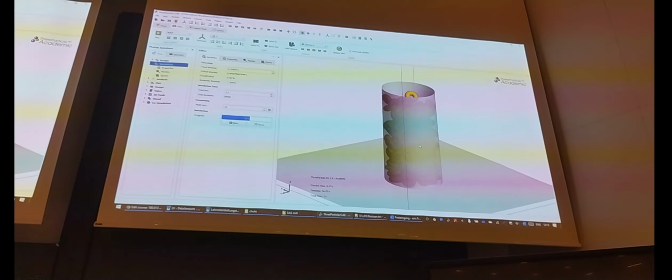If I increase the time step to a certain point, let's see what's happening. I increase it to 0.01 and I start, and the thing suddenly starts moving at some point. Okay, that seems kind of critical, on the limit. Let's increase it even more. And boom, unstable. Going back. And again, so I find out which time step leads to an explosion of the system, right?